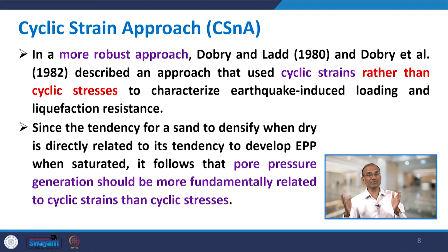When you have a saturated sample, there will be development of pore pressure. So, both are related. They are fundamentally related to strains, cyclic strains, rather than cyclic stresses.